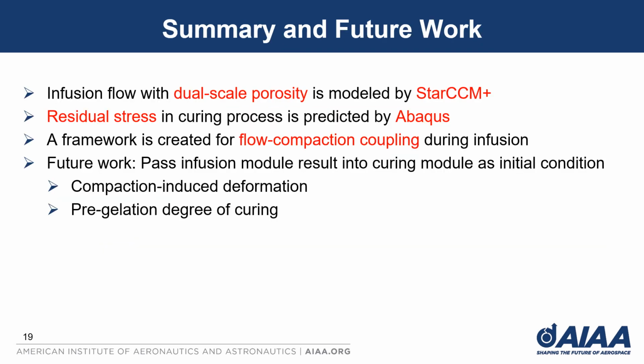In summary, we use STAR-CCM+ and Abaqus to model the infusion flow and residual stress in the liquid composite molding process. A coupling framework is demonstrated by a flow-compaction coupling example. Future work includes passing the infusion modeling results as the initial condition for the curing model, for example, the compaction-induced deformation as well as the pre-gelation degree of curing.